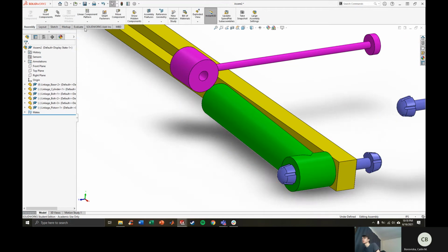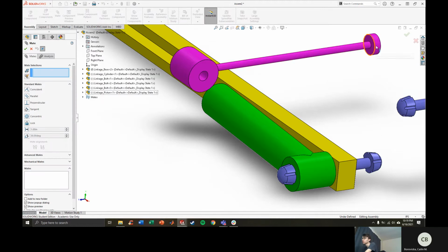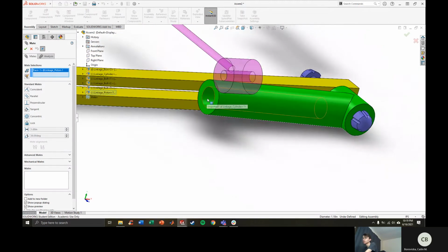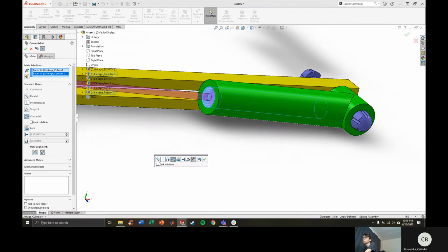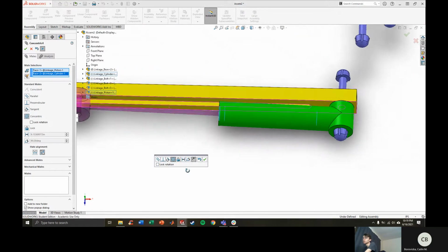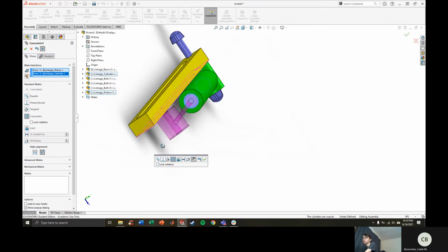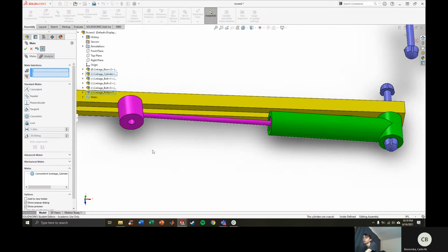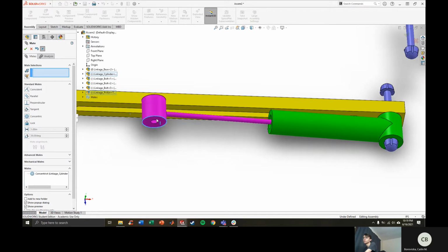Again, just kind of open it up, click it wherever you want. The piston, same process basically. So that's the side that's going to go in the cylinder. So you can select the outside of that, select the face. We won't lock rotation because the rotation is determined by how this face mates with the base. So you don't want to mess that up. That's good.